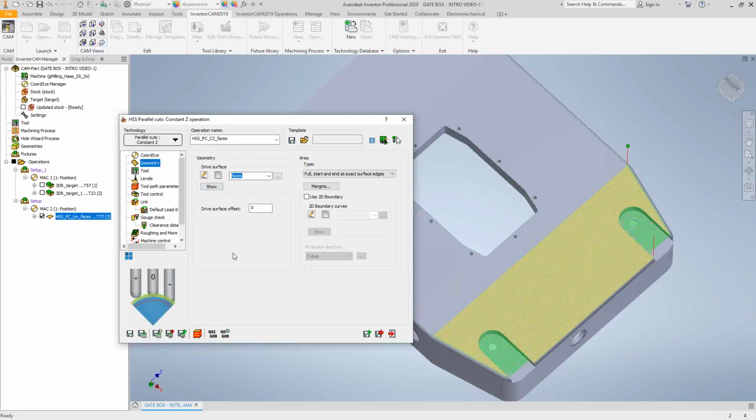It's a waterline cut. This actually is somewhat of a better toolpath if you're doing more vertical or near vertical surfaces, because you can actually control it so that it's always moving in the z direction. And if there is a surface that is not in one particular direction, then constant Z allows you to kind of slice it up in that same level, so you actually get toolpaths that change direction. It's not just in one direction, you can do curves and such. So everything else here is approximately the same.